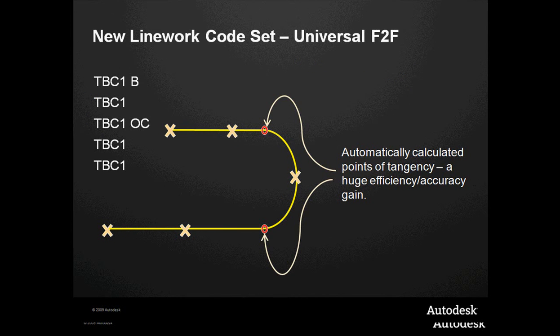If ever you've had guys in the field walking around a curve return or islands or something like that, you'll have an expansion joint or something you can take a shot on, but if they don't hit the exact PC or PT, when the line work's drawn up, you have kinks. The arc comes around and there's a kink that goes to the line, and then usually the engineers start crying about that. They want that straightened out and looking a lot better.